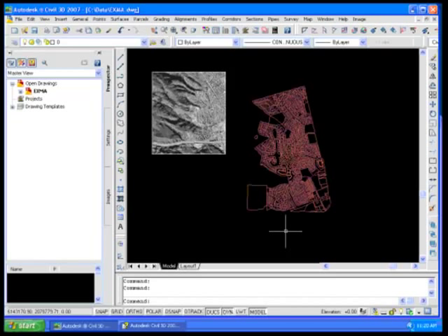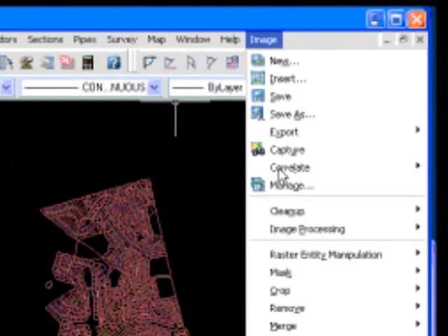So if you've got unevenness of terrain or parallax errors, or there was a problem in the scanning, or if there were issues with the lens distortion when collecting that image, there's a very clean and a very effective way of just translating key control points on that raster image to key control points on the vector data. So now you have vector data overlaid on top of your raster image. It gives you a very nice visual. So this will take me a few seconds here, and I'll show you how that's done, and then we can get into the DEM aspect of things.